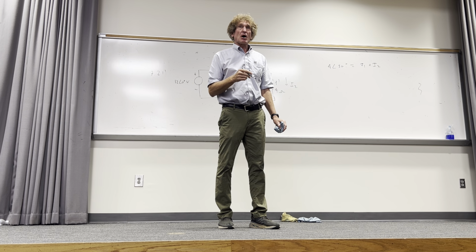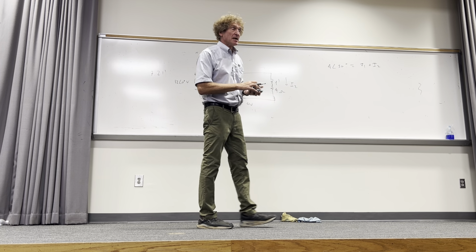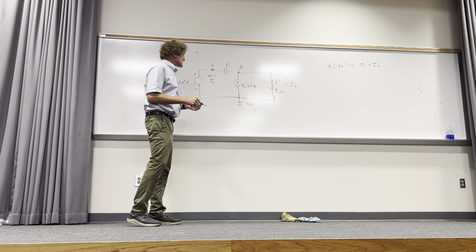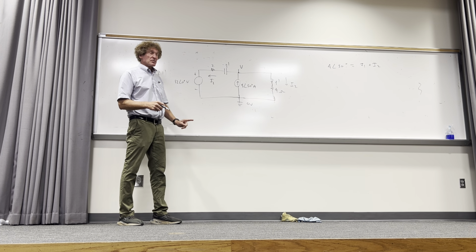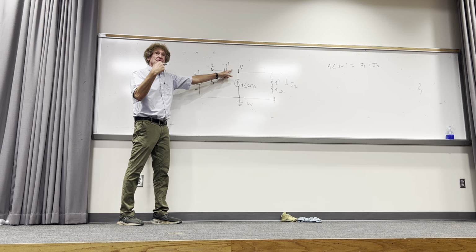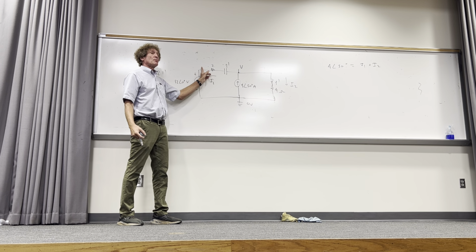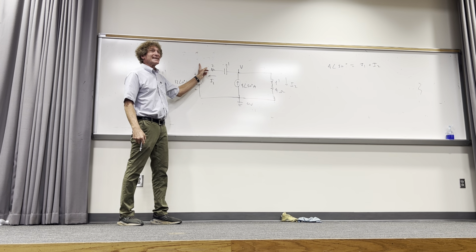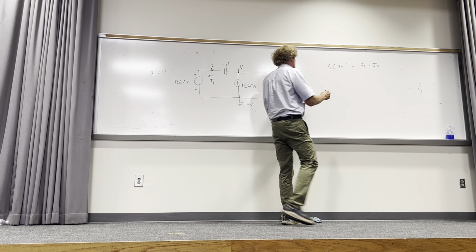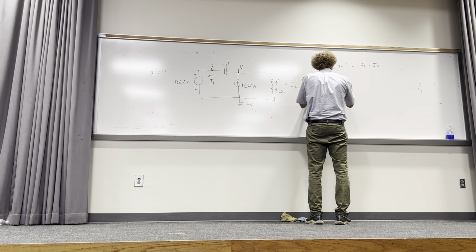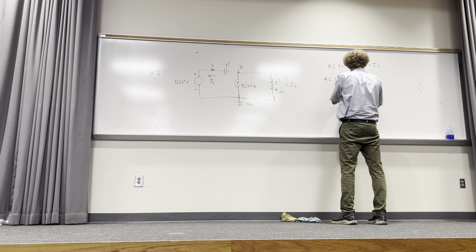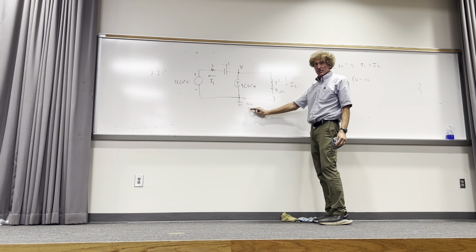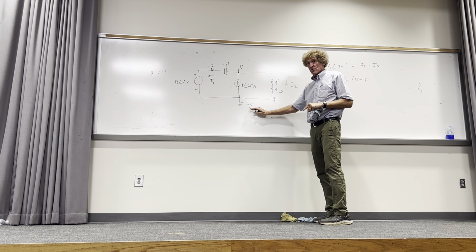Now, here's where you're going to have to use your calculators to calculate this, and then they're going to be complex numbers. When I look at this, what is I1? Now, be careful. I1 is always going to be the voltage on the point where the current enters the impedance minus the voltage on the point where it's leaving the impedance, over what? The impedance. You all agree with that? So here, I'm going to have 4∠30° equal to I1, and that's going to be V minus 12. You'll notice I grounded that, so every voltage is with respect to 0 being the ground. You all see that, class?